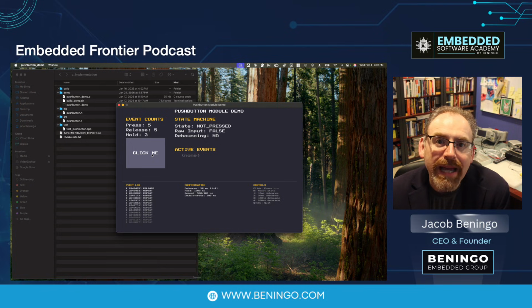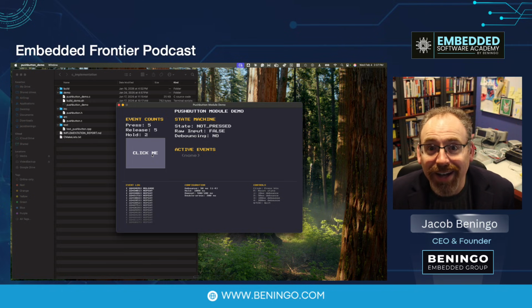If I decouple my debounce code from the physical hardware itself by having a nice modern software architecture, this opens up the avenue to use so many different modern techniques to develop my embedded system. Ultimately, what this allows us to do is work faster. I think it's smarter, and it certainly allows us to deliver firmware much more efficiently and cost effectively.